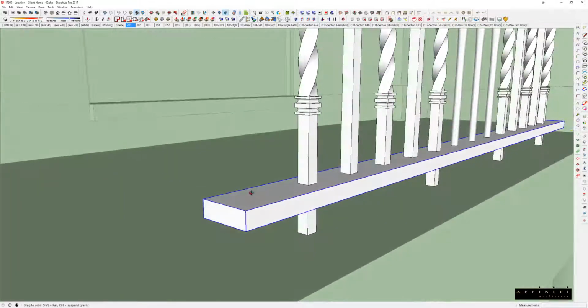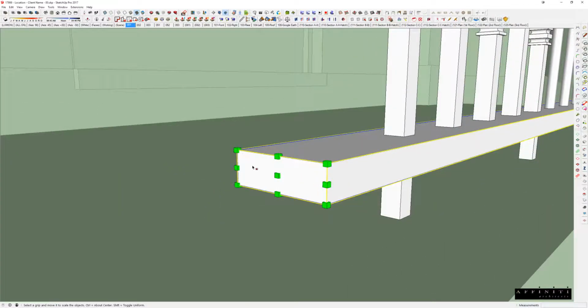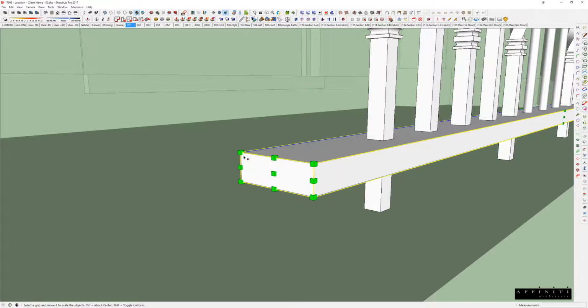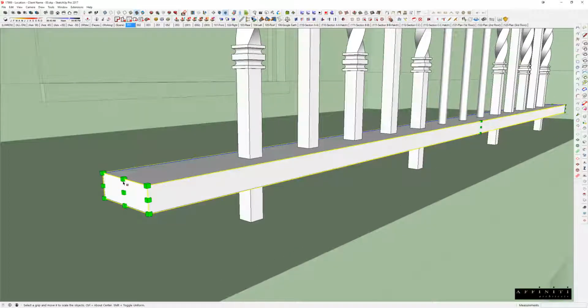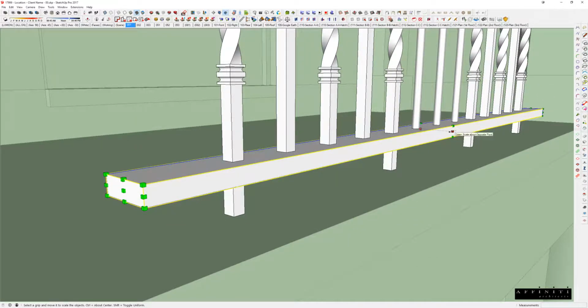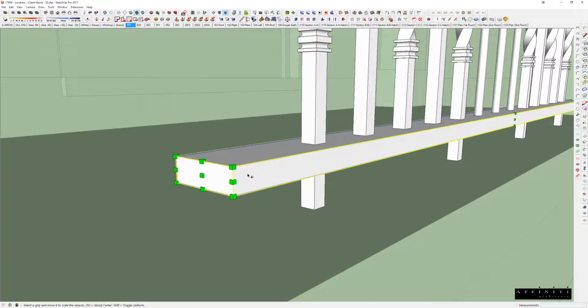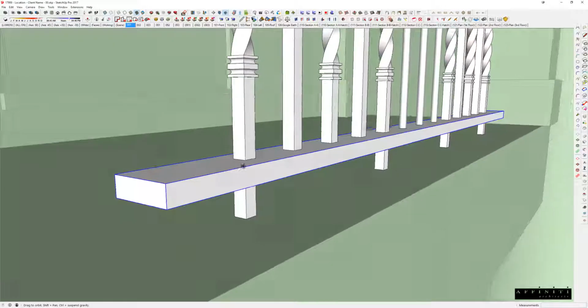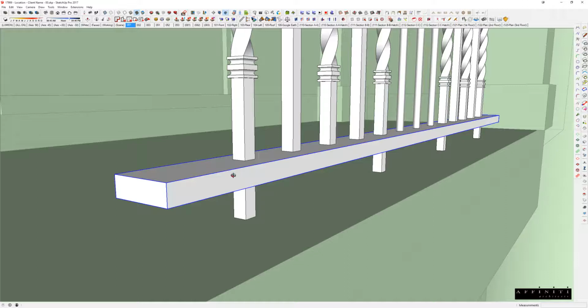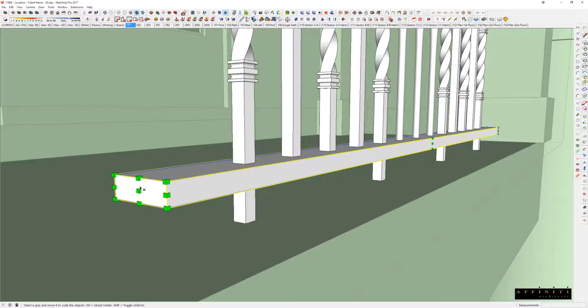I'm sure you guys all know how to use the scale tool, but just a quick discussion on it. You have these 9 different grips, at each end and in the middle. We can talk more about scaling later if you have questions on what these are. But specifically what I want to look at is this center one. When I grab this grip here, you see that it's kind of small, but there's another red box that lights up, which means it's a mirrored grip.